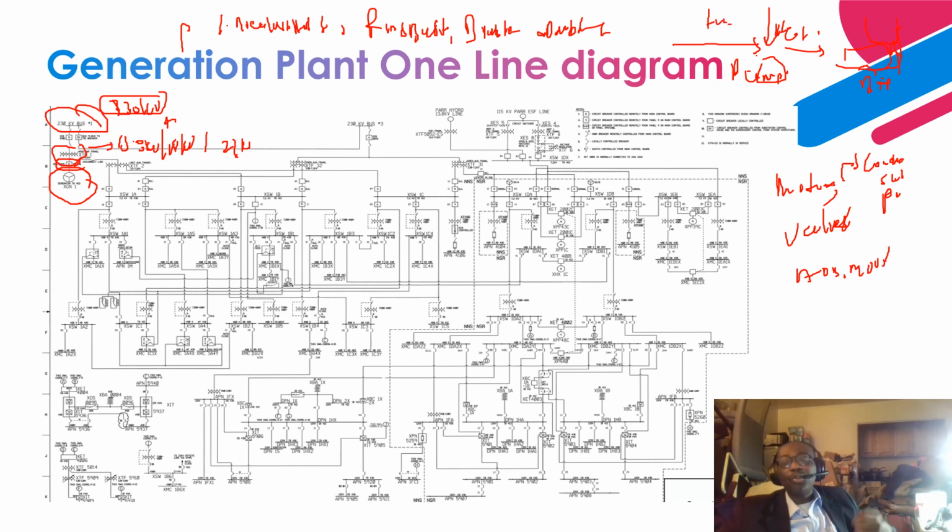So it utilizes that amount of steam to basically heat the feed water system before it gets to the boiler. This is part of basically the efficiency. You're trying to improve the efficiency and basically extracting heat from the steam that is already flowing into the turbine, right? To warm up this feed water heater that is basically going to go to the boiler.